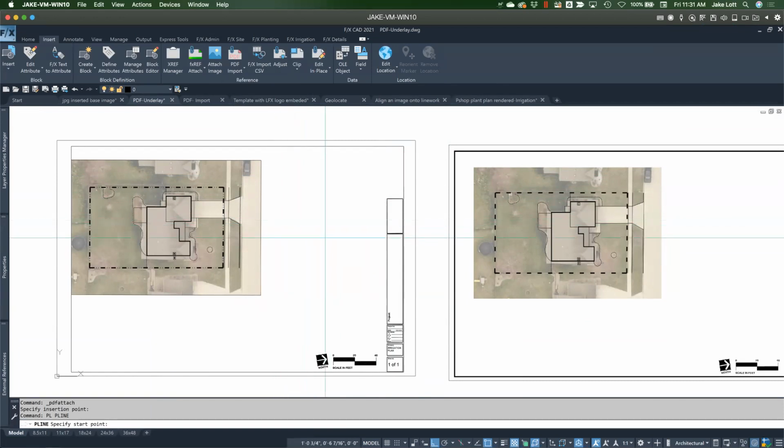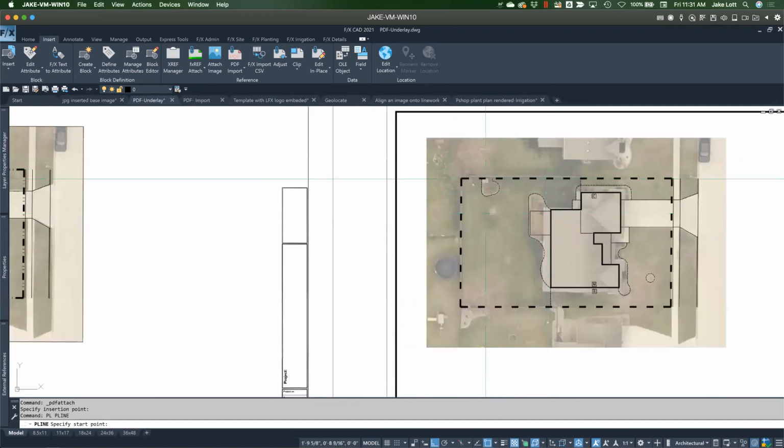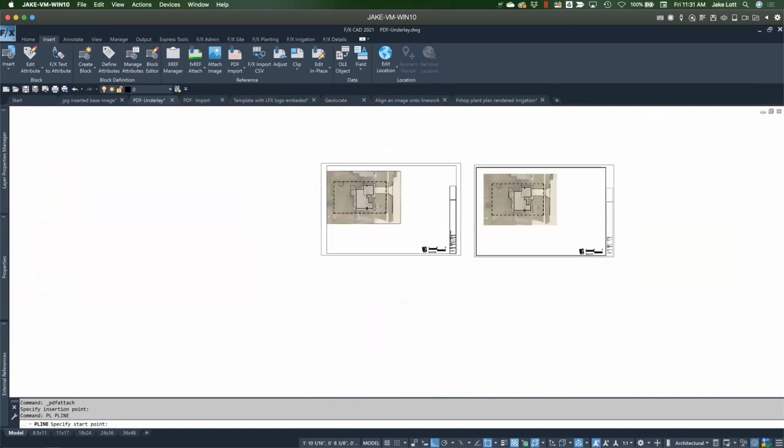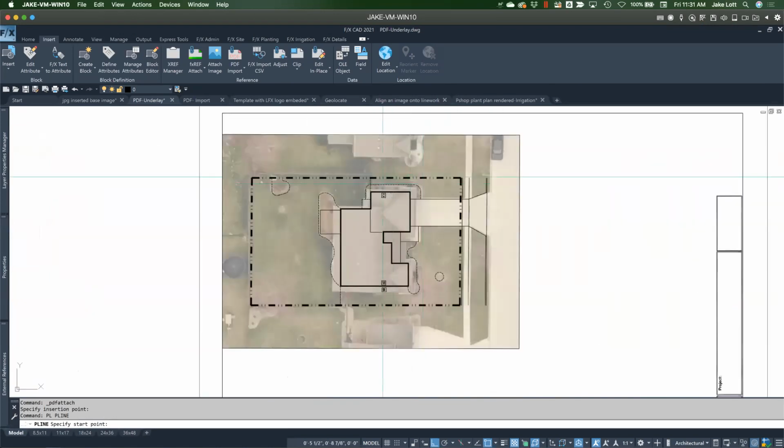When we're doing polylines or any kind of object snapping in a raster image style, you can see that it's connecting to the borders of that image because it finds it, but it's not seeing any of this line work, right? And so we're tracing this to the best of our abilities from that line work. But if you come over to a vector-based PDF, generally something that was generated out of CAD, you'll be able to see this.